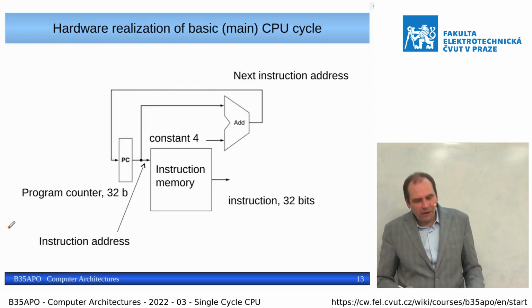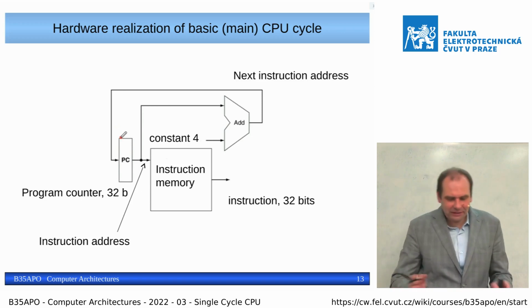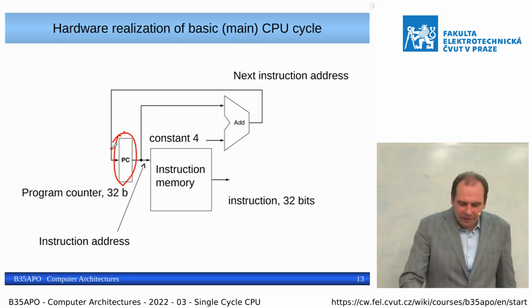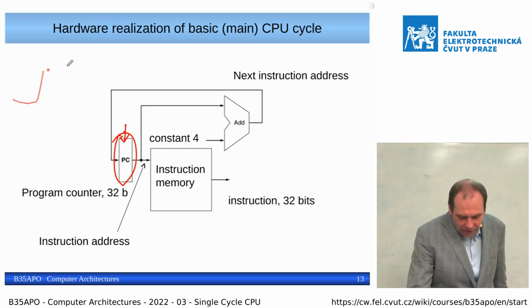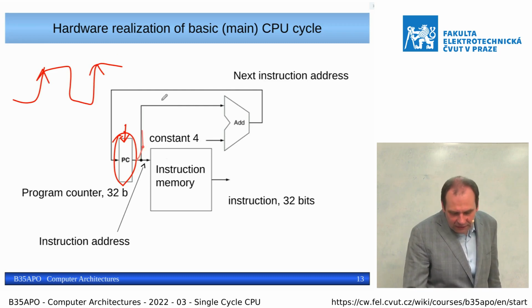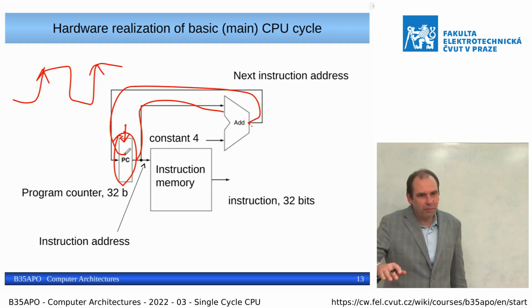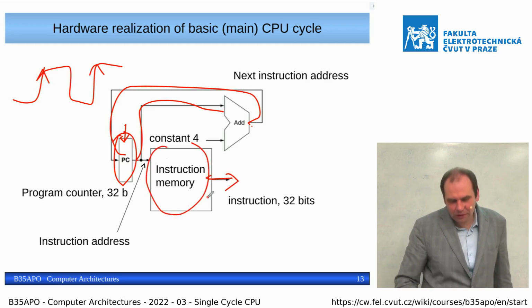And to process the instructions, basically we need, okay, there are general purpose registers, but the PC is a register as well, a specific purpose register. At each clock cycle, if the instructions are processed in some period, we advance that register by 4. That way we move to the next location in the instruction memory, so we read the actual instruction.